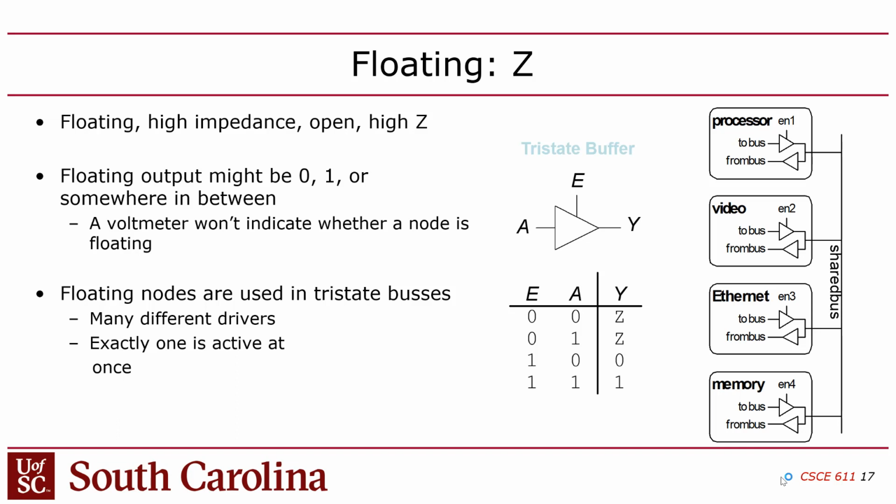You have to buy a license. The problem with Verilator is that it doesn't obey the 4-state logic. It only goes 0 or 1. That's why I don't use Verilator in this class. I don't like Verilator because if you double drive, it has just undefined behavior.